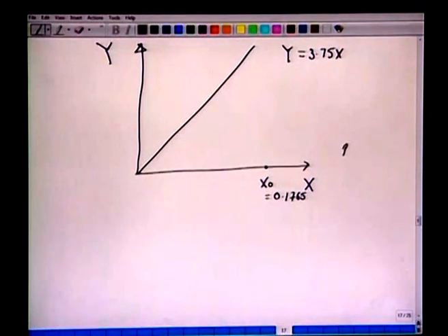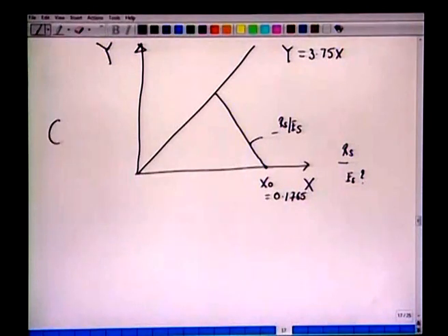We know Rs, right, but we do not know Es. Es is not known to us. That means we cannot draw this operating line which has a slope of minus Rs over Es. And the two streams which leave stage 1, y1 and x1, we know they are in equilibrium, but we do not know y1, nor do we know x1. So this point is also not known to us.